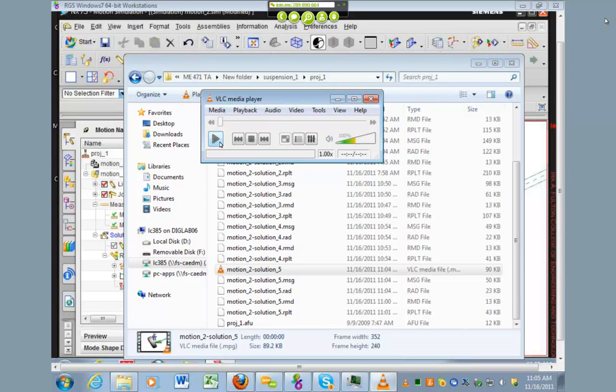You could even take your motor and make that the driving joint. And if you set up all the other joints, you could have that driving gears and have the gears driving other gears. And you can actually put joints that represent gears. You don't have to have a modeled gear. You can just make a joint that says this simulates this size of gear and that size of gear.